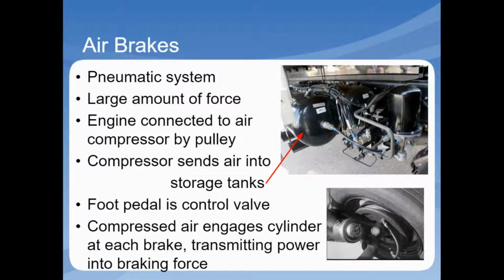The driver's foot pedal is a control valve, and when it's activated, the compressed air from the storage tank engages a cylinder at each end of the brakes. Through mechanical linkages, a cylinder transmits its power into a braking force.